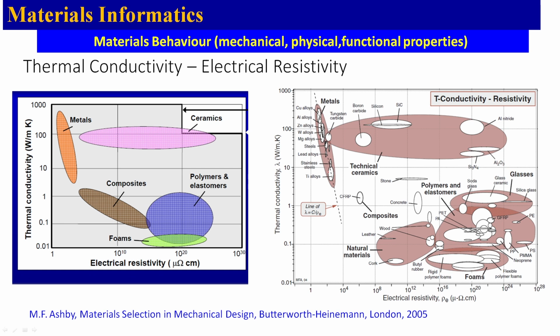You may say that yes, we know about it, but the chart also tells you, if you want to find some alternatives to copper, what all you can choose. The next alternative should be aluminum. That is what is done in air conditioners. If you have seen air conditioners, the pipes inside are basically made of either copper or aluminum. Similarly, electrical wires can be either copper or aluminum. So, these are all experience based, but the theory or the data science also provides strong confidence on that. That is what Michael Ashby's charts can provide.